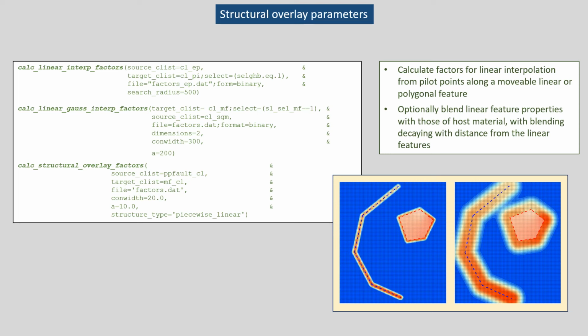Now, interpolation can be conducted down the polylinear segments which comprise the feature or within the feature. This is undertaken by certain PLPROC functions, and then interpolated values can then be blended with the properties of an underlying model grid, that is a P-list belonging to a model grid C-list, using other PLPROC functions.